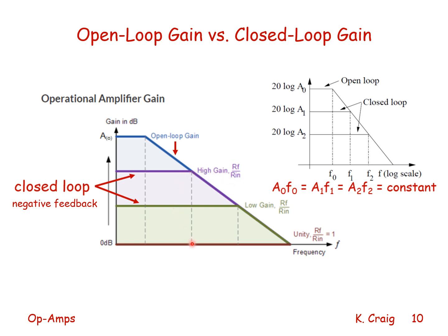But at a frequency, that gain can never exceed the open loop gain. So once we get to a frequency where this horizontal line runs into the open loop gain, the gain then will follow the open loop gain curve. We see another diagram over here to further explain the relationship between the open loop and closed loop gains.